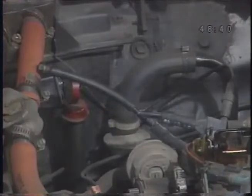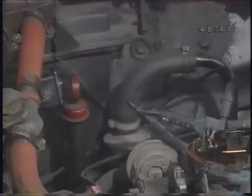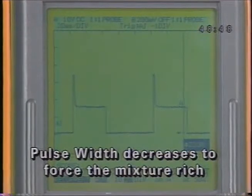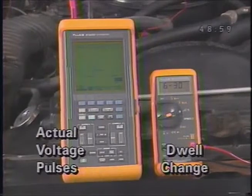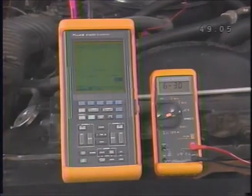Then try checking the pulse width again, this time with a vacuum leak, creating a lean mixture. See how the pulse width changes? If the system's working correctly, the pulse width should decrease. The pulse width change is identical to the dwell change you're already familiar with. But now you're watching the actual voltage pulses as they happen, instead of just an average change.